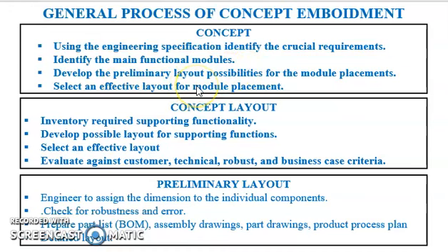After this, the overall layout of the product is drawn to a scale based on rough concept drawings. In these drawings, specifications and maximum dimensions of a product, clearance between the relative subsystems, installation path, and general arrangement of the concept with respect to each other are depicted.